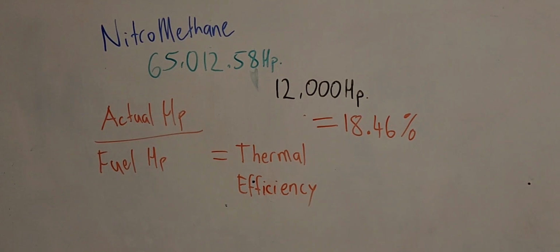Using some basic sums from before, using the HP per pound, and using a basic sum that a nitromethane top fuel dragster will consume about 4 litres a second of nitromethane. When we project that out over the course of a minute, we'll wind up with the theoretical horsepower potential of just over 65,000 horsepower. It has been worked out to be that, but it is an approximation because there's no real dyno that you can put this on and get an actual figure.